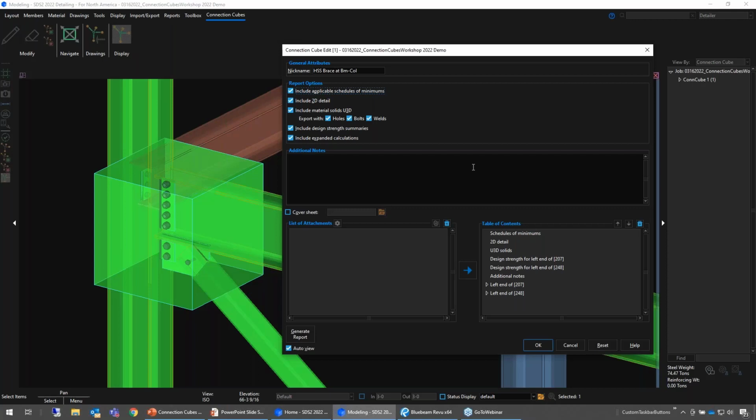We have seismic activity, so designing my brace like this would be really important, and I'd focus in on these guys early on, trying to size the gusset and whatnot. Like I mentioned, I had a few spreadsheets shared with me, but I felt it was safer to mainly stick with my own calc so that I could control the design myself.